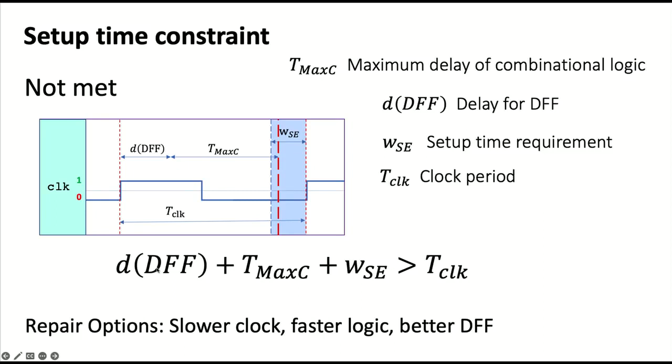Yeah? The setup time and the hold times are properties of the flip-flops you get. And the delay of the flip-flop. Those are all properties of how you built your flip-flop. And if you build it carefully, you can try to minimize these. Okay. All right.